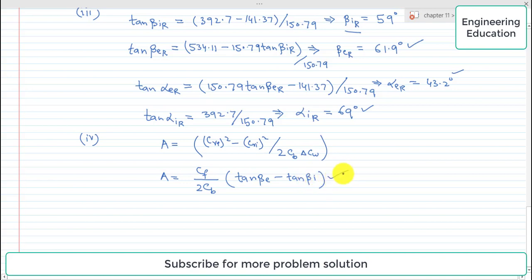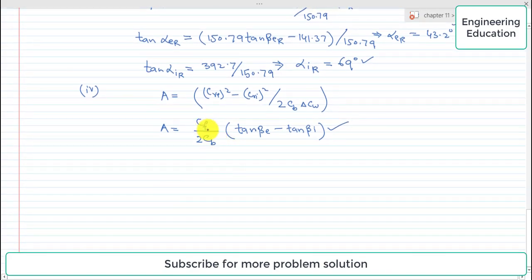Now to find the degree of reaction at tip, for that we will use CF is constant and its value is same for both tip and root. Only blade velocity for tip will become CBT, and beta ET, beta IT for tip. Similarly, when we are finding the value of degree of reaction for the root, in that case the subscript R will be used, CBR, beta ER and beta IR. So I am directly putting the values.